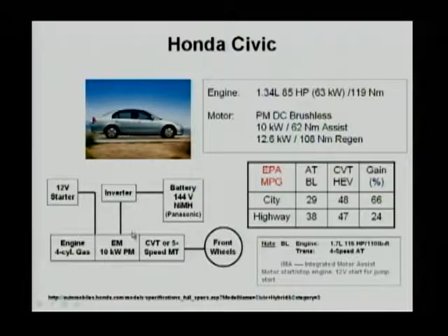And the motor is powered by an inverter, and the inverter takes power from a nickel metal hydride battery, at 144 volts. So this is also called a common shaft design, and it is a torque coupling. It is a parallel hybrid. Even though position-wise, it looks like a series from engine to motor to vehicle, energy flow wise, it is a parallel hybrid.